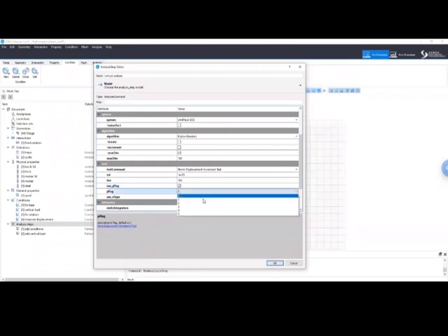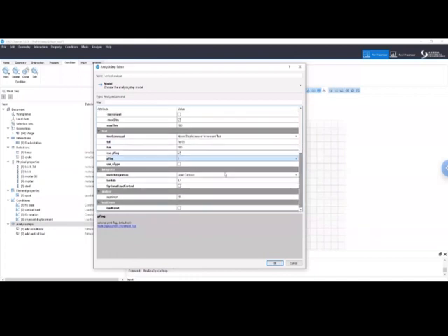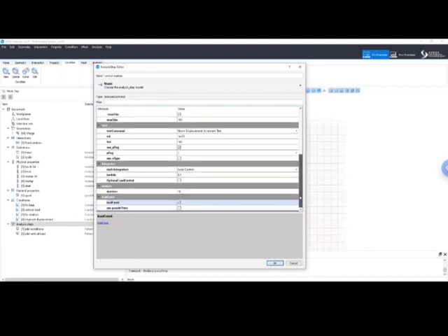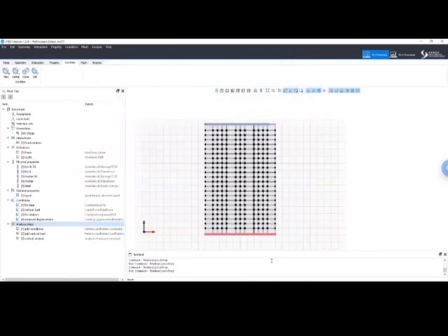And we also want to print them. We just want to print the convergence, so we see if the model has some problems. And for the first analysis, the vertical analysis, just 10 time steps at a lambda of 0.1 is sufficient. So at the end of this analysis, we want to keep the vertical load constant, and we want to reset the time step to 0, so that we can start with the second time series here. We press OK. Now, up to here, we are ready for the first analysis.